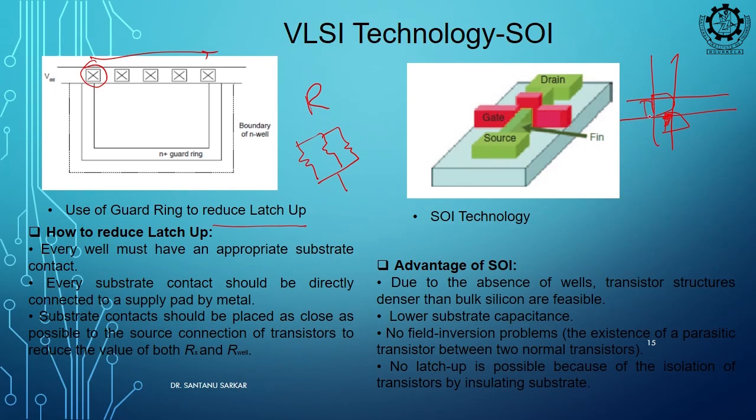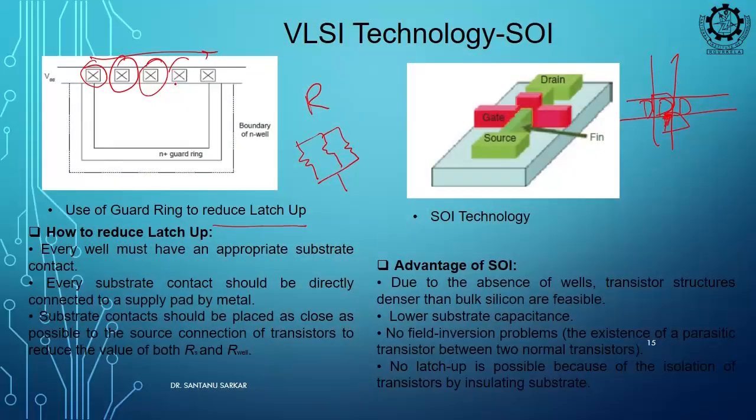But if you have multiple contacts, then your connection is strong. Drawback? Obviously, there is a drawback, you are getting more area for the shorting. So there will always be a trade-off. More contacts, more solid connections, but the area is getting more. So if I can have multiple contacts or p-taps for the substrate connections, then my resistance will go down.